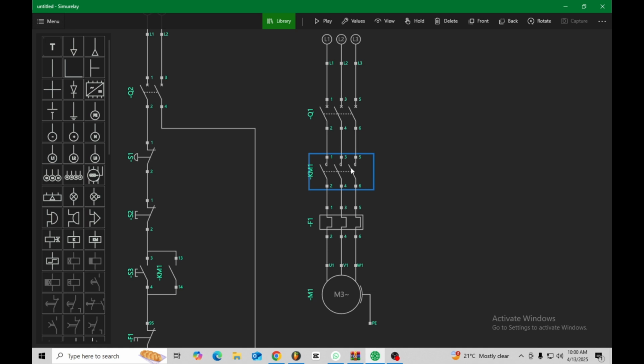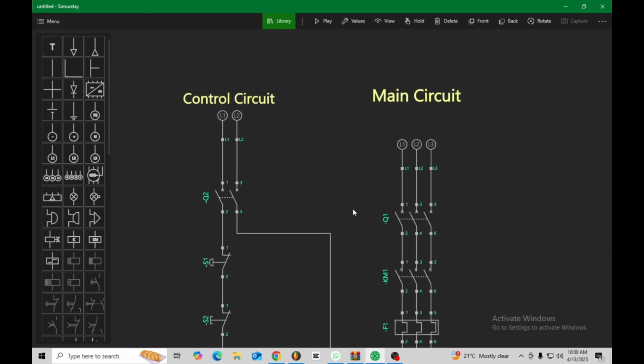After your contactor, it goes to your overload relay, which is there to prevent further damage to the motor, which is this one, in case there's any trip condition or earth faults or anything like that. So if your earth leakage is breaking down or something like this, this bad boy is there to prevent anything from stuffing up. So that's your main part of your DOL. So let's go to the control circuit.